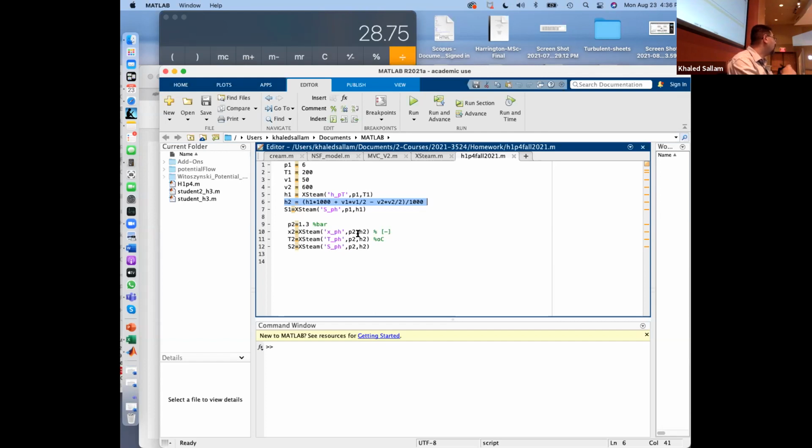For mass, if we want to stick to English units, we don't use pound mass, we use slugs. But at the end of the calculation, he wanted BTU per pound mass, fine. I just convert in the last step. Okay? So that's my advice.